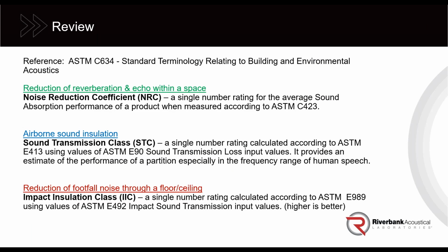And finally, in review, sound absorption is classified by the noise reduction coefficient, or NRC rating. NRC is specifically related to the behavior of sound within a space: echo, reverberation, sound reflections. Sound transmission class, STC, is specifically related to airborne sound transmission through a wall. And then impact insulation class, IIC, is related to the footfall noise that you hear in the floor ceiling assembly above you.